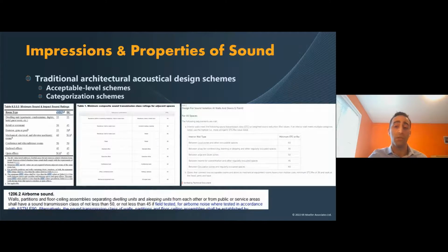Given that STC uses laboratory data, it has become a general rule among acousticians to accept NIC values that are within 5 points lower than the design criteria, or an ASTC value within 3 points. The most common reasons for significant deviations include improper design, inconsistent design, and/or poor construction. As you can tell, there's tremendous allowance for uncertainty, one for background noise and one for sound insulation. This further enforces the benefits of using masking sound as an adjustable solution to enhance acoustical performance of a space.